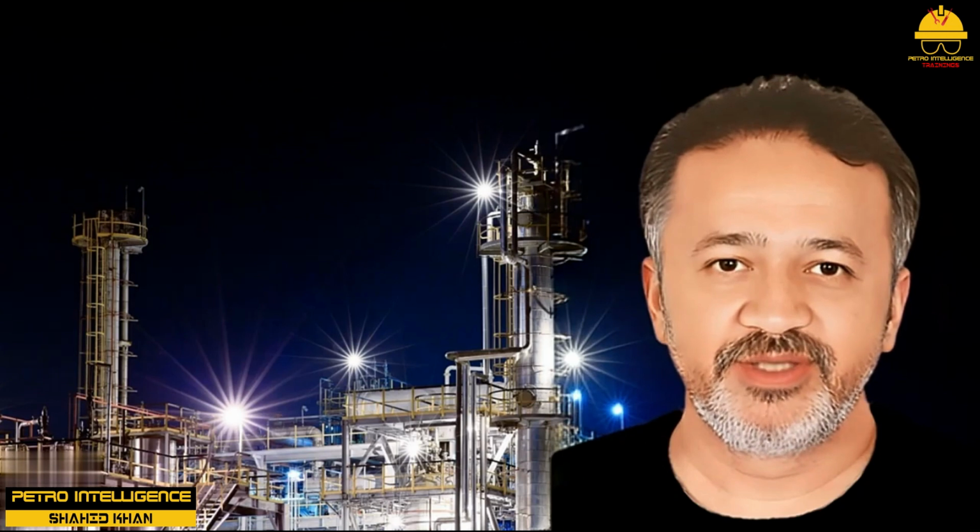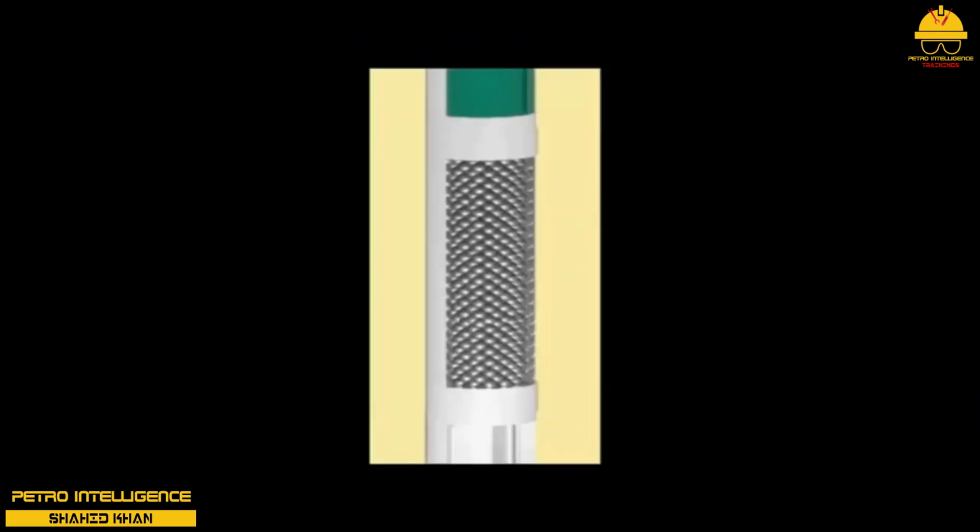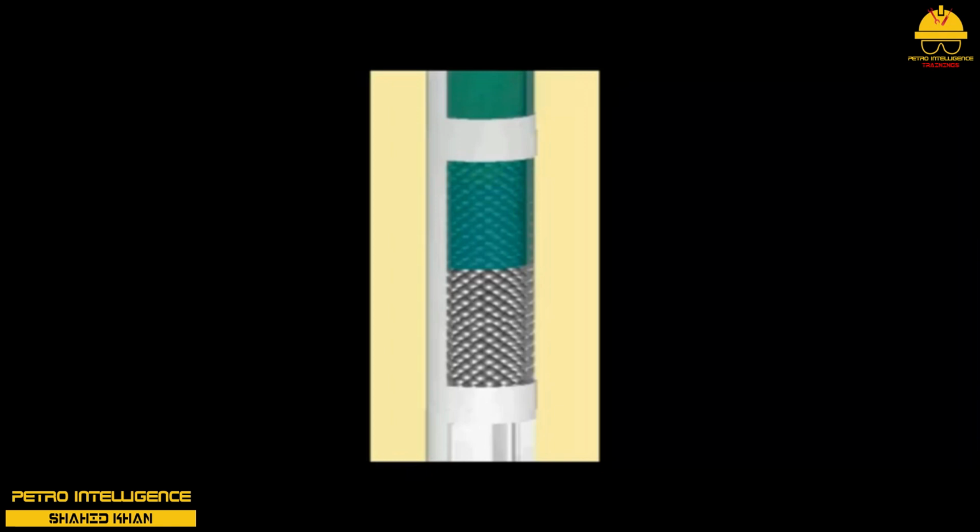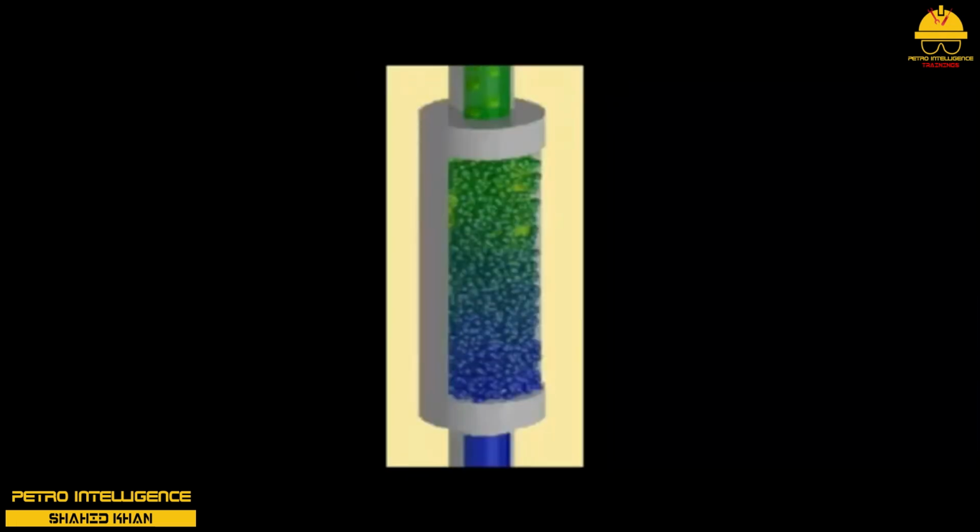Fixed bed reactors. A fixed bed reactor, often called a converter, is a vessel that contains a mass of small particles, usually 0.1 to 0.2 inch in diameter, through which the reaction mixture passes. The mass is usually a packed bed of catalyst, which promotes the reaction. The mass could also be column packing such as Raschig rings, berl saddles, or marbles. In this case, the packing creates more heat transfer surface to give better heat distribution in the converter.